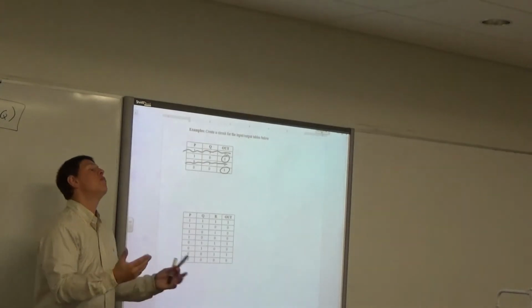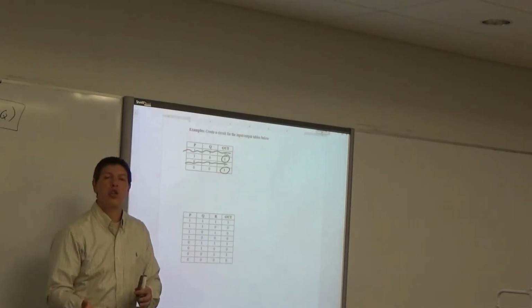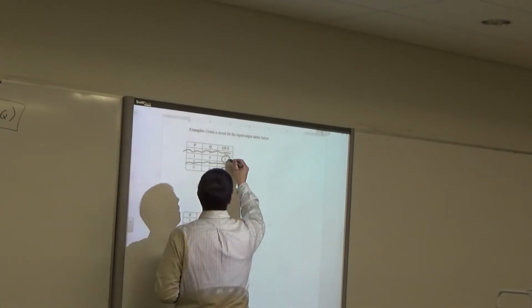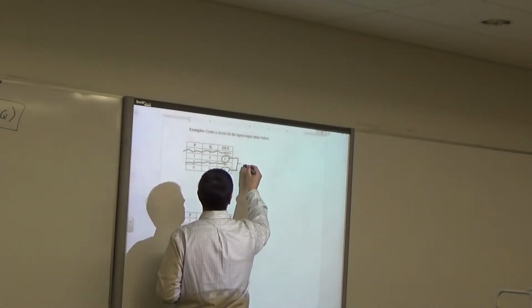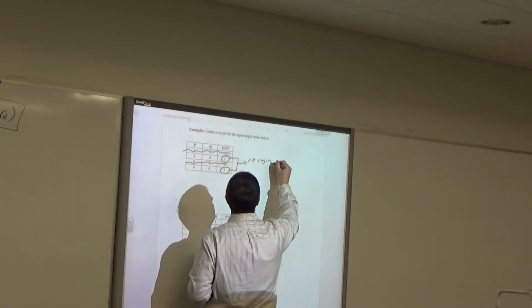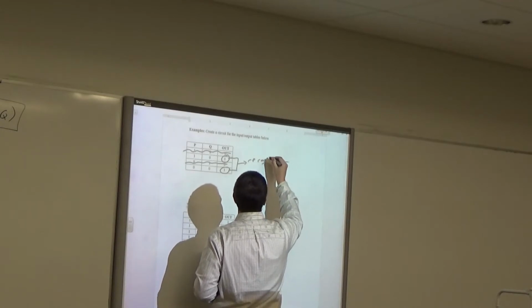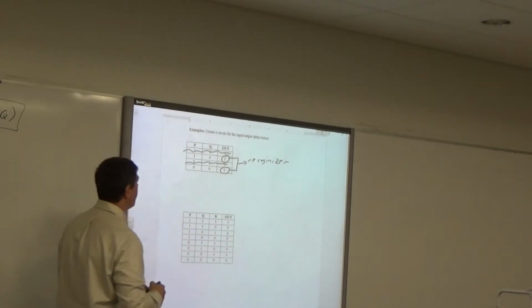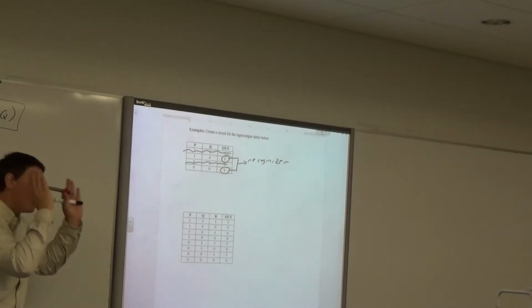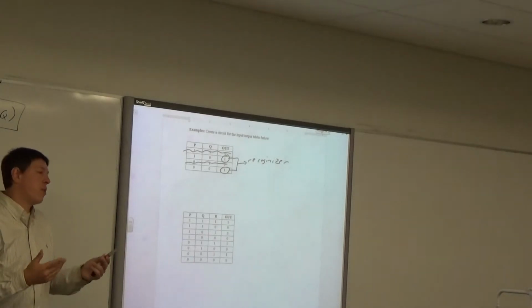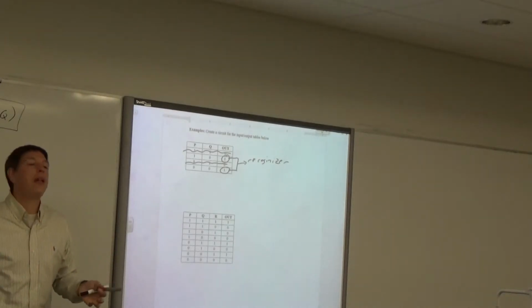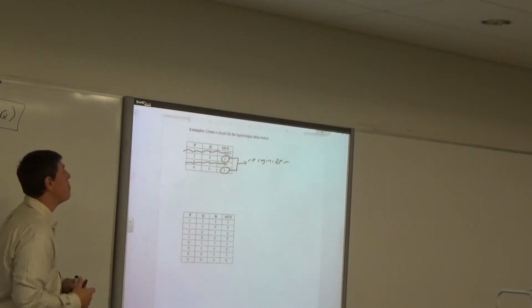Okay? In computer programming or computer architecture, we call that a recognizer. Okay? So any row that has a 1, okay, that animal is called a recognizer. We don't care about the other rows. Okay? Like I said, this is not the most efficient circuit. So what somebody does is they make a circuit from what they have here, and then they might use some Boolean algebra to simplify it. Okay? So let's actually make the circuit.